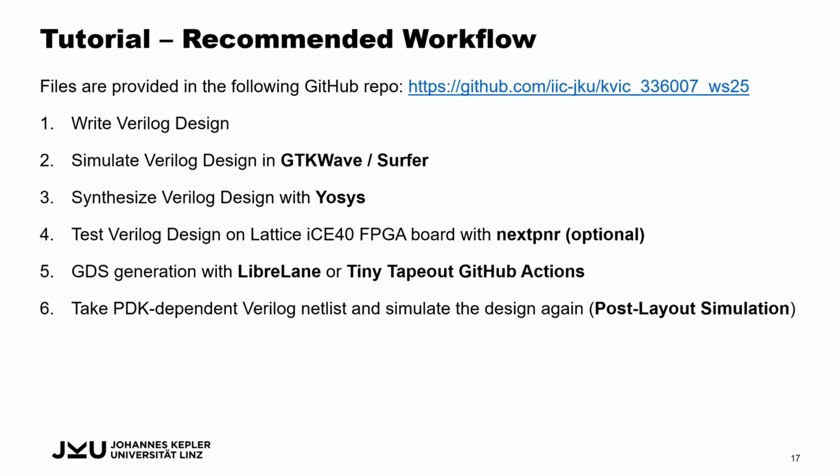And finally, after the LibreLane flow, there is a final Verilog netlist, which is also used for LVS, layout versus schematic. This netlist in the end contains, for example, additional registers or buffers, if they are needed for the clock tree synthesis or for the clock tree itself. Then you can also simulate this Verilog netlist again with GTKWave or Surfer, for example, and check if everything still works.